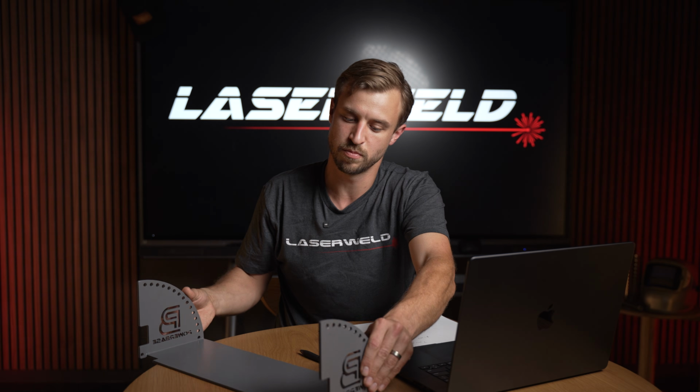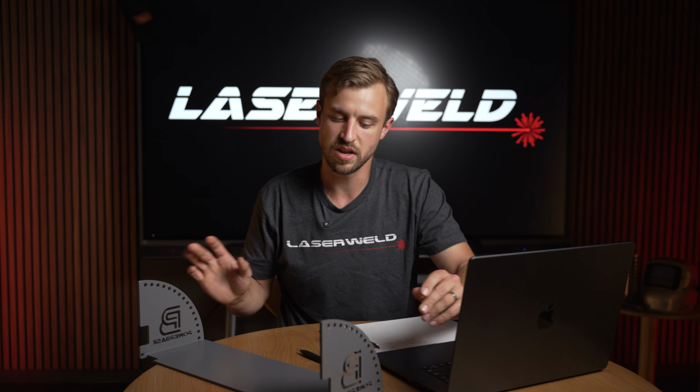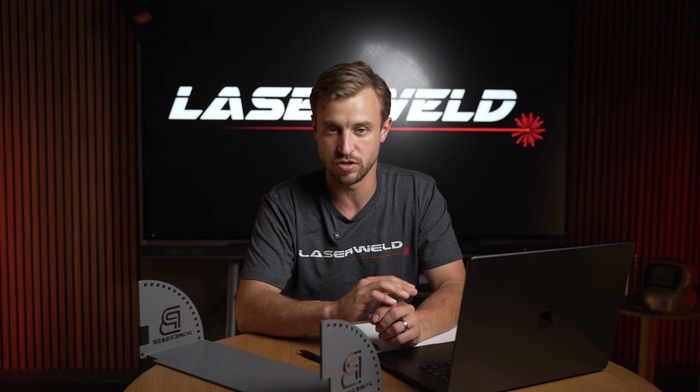If your part weighs 1 pound, it took you much more than 1 pound to produce that part. So that's why we go off the plate weight. If you just put this on a scale and weighed it, that's your net weight. You need to quote the gross weight. And that's why we take the plate weight divided by the total number of pieces.